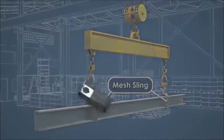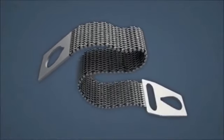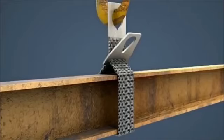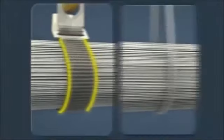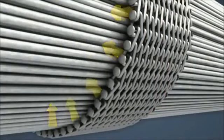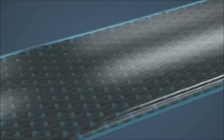Metal mesh slings are made up of small, connected metal rings or other shapes. This results in a mesh sheet that is flexible and has a large surface area. Metal mesh slings are widely used in metalworking and other industries where loads are abrasive, hot, or sharp. The wide surface area of the mesh prevents single-point stresses that would occur on wire ropes or chains. Also, metal mesh grips the load firmly without stretching and helps maintain a balanced load. To prevent the sling or load from being damaged, sometimes metal mesh slings are coated with rubber or plastic.